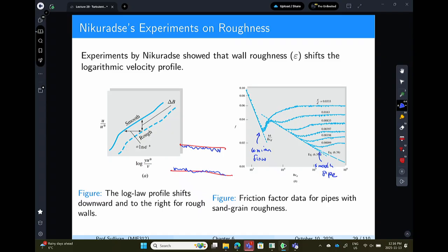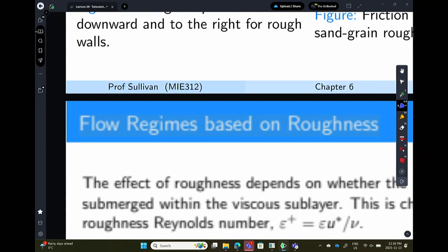And here are different results, friction number versus Reynolds number based on diameter. Different results for differing levels of roughness. At the very top you have 0.03, and at the very bottom you have 0.00099 of epsilon over d. Again, small roughness element, small height. You can think about this as sort of sand grains thrown in a pipe. So you can have a 1 meter cross pipe with sub-millimeter scale grain of roughness on it. So you have that sort of partial description.